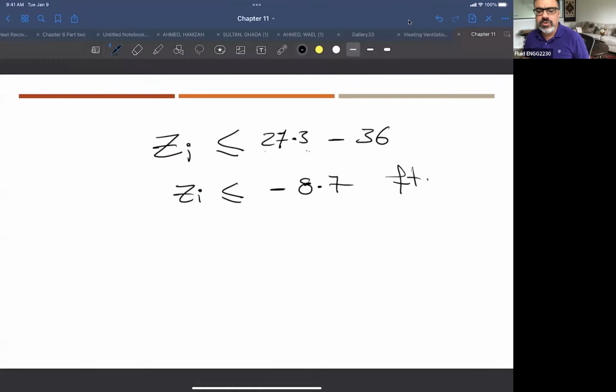Why? Because now this criteria will be the opposite. That means the pressure, which is 14.7, reduced by losses of 6, reduced by the vapor pressure, and the liquid now evaporates, right? Because the value will be closer in this case, right? So the equal value here is the minimum, right? But you can actually increase or decrease this location of the pump. Decrease means here, you put the pump even more down, right?